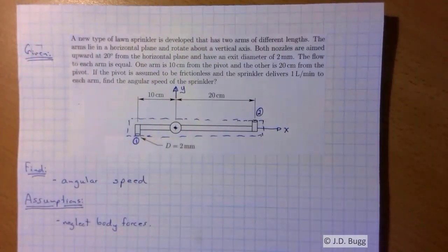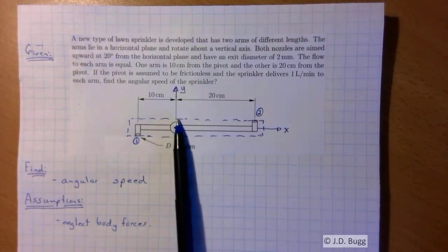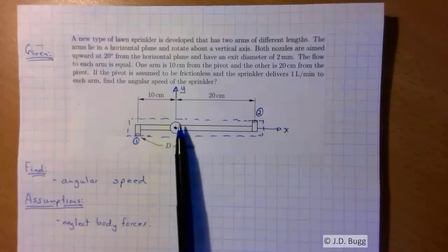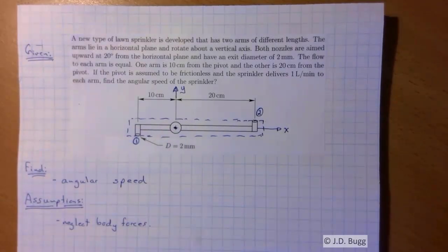Now, a moment ago I talked about the fact that, hey, we got to remember there's an inlet here. So remember, our control surface does cut through an inlet pipe somewhere. Not really shown, but it has to cut through an inlet pipe. Well, the pressure in that inlet pipe will be higher than atmospheric because it's driving the flow through this system.